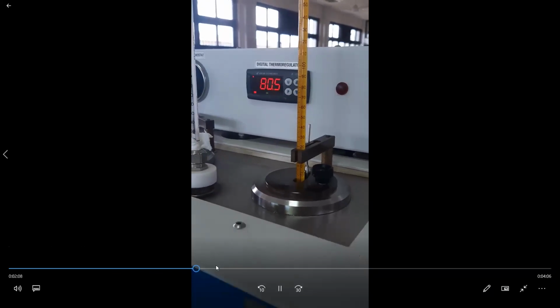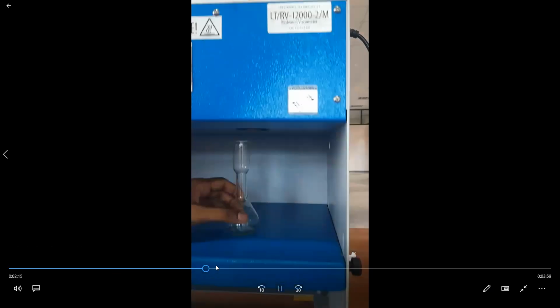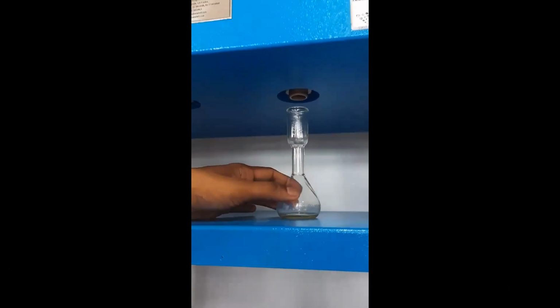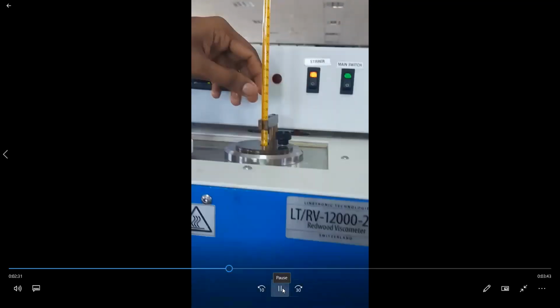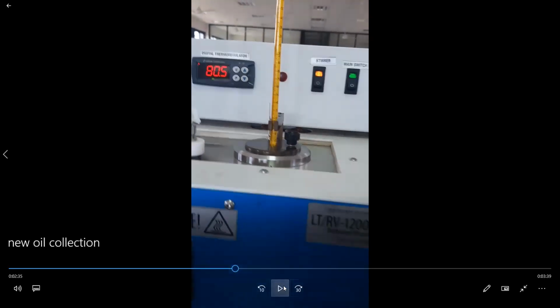Here you can see, I already explained, under this cylinder there is an oil orifice hole. So we have to place this cup under this orifice hole. After we remove this ball valve, we can start to collect the oil sample. While we are removing the ball valve, we have to start the stopwatch. That is the point we start to collect, right? We have to let the stopwatch run up to the 50 milliliter level.